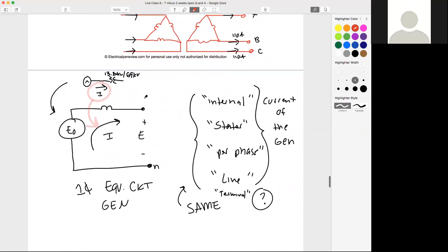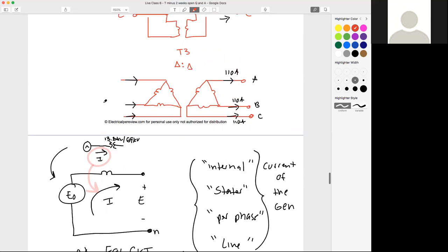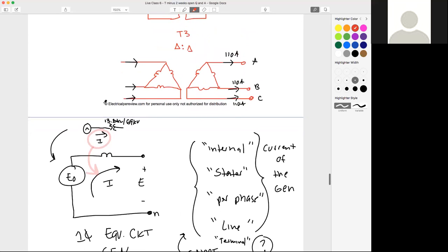No problem. Eric asks, since we're talking about equivalent circuits, when do you use an equivalent circuit as opposed to a synchronous or induction motor circuit? Eric, that totally depends on the machine. This is a synchronous generator equivalent circuit, looking just at the stator. Any large-scale generators are always going to be synchronous generators.